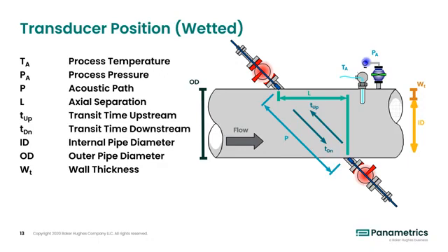One important thing to note is that this is the actual volumetric flow rate. For many customers, regulations exist that require flow to be normalized or standardized to certain temperature and pressure conditions. For this, our flow meters can accept a live temperature as well as a live pressure input from field transmitters. You can see those in the top right of the pipe. This standard volumetric flow is often represented in terms of standard cubic feet per hour, SCFH, or standard cubic meters per hour, SM3/H.